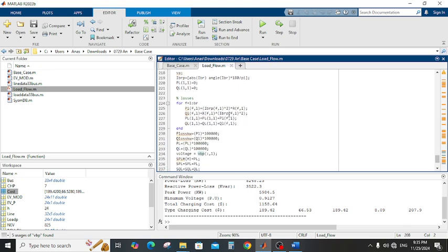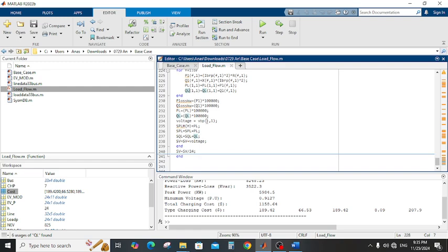Now we start to calculate the power loss and reactive power loss, as you see here, and accumulate them. We also calculate the voltage, and this process is repeated and accumulated, giving the power loss for each hour. After we finish this process, we have finished 1 hour, and this process is repeated for each hour for 24 hours and accumulated in these 2 or 3 variables.